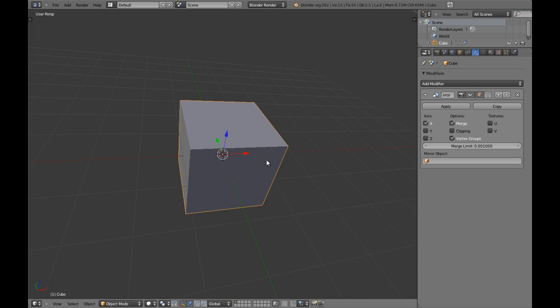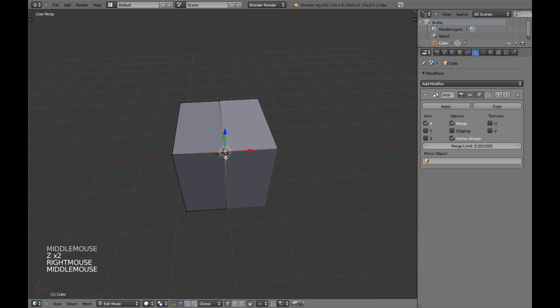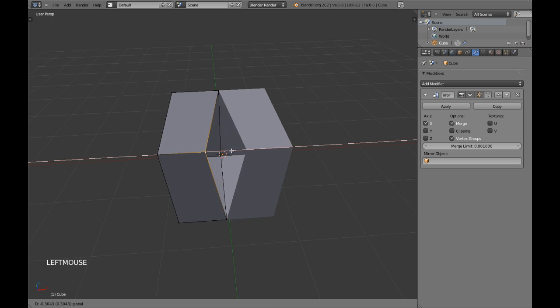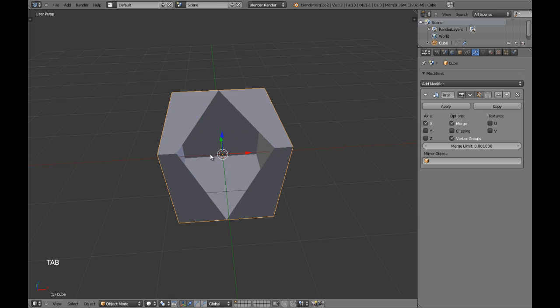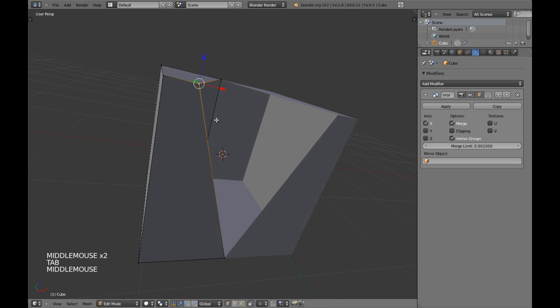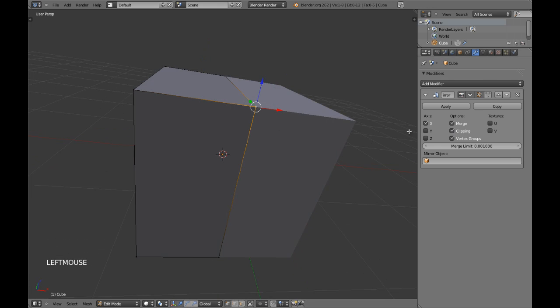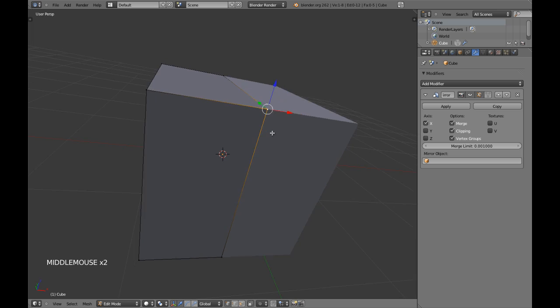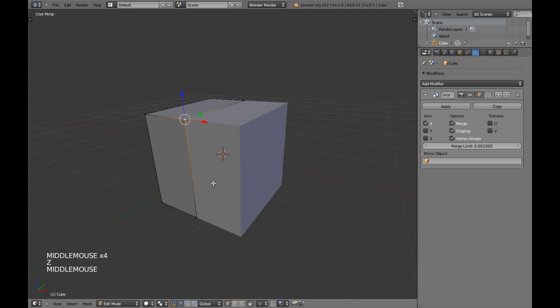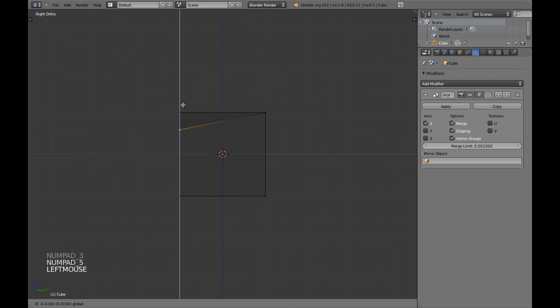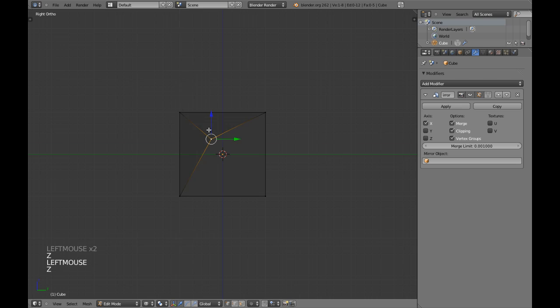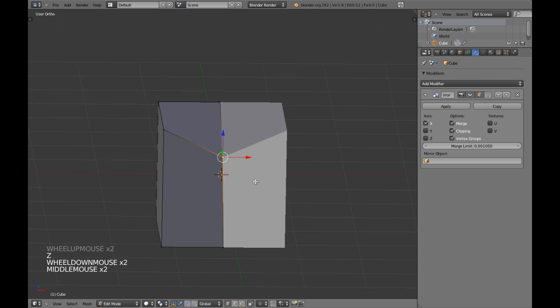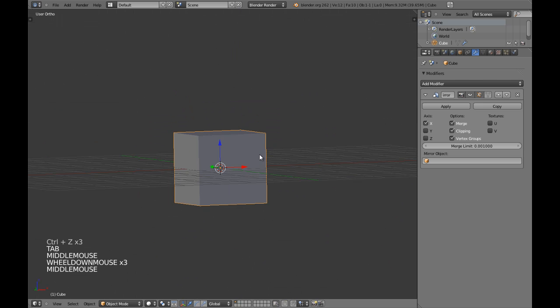And really quickly, I will explain what clipping is. For example, if I want to move this vertex in the x-axis, Blender allowed me to do it, and we will get, well, this hole here. But if I enable clipping, Blender will tell me that, well, this is the middle point, and you are just not allowed to move that, because you will make a hole in this object. So that's how clipping works.